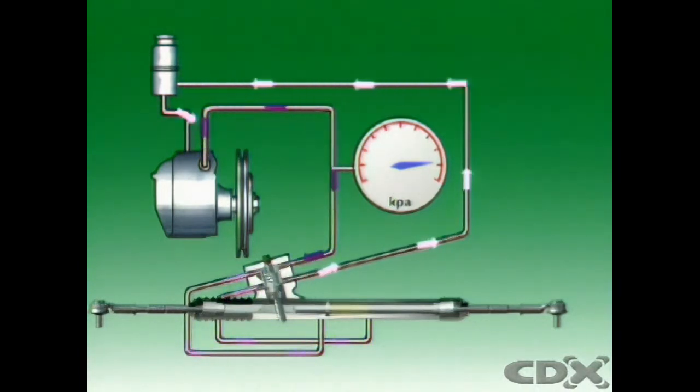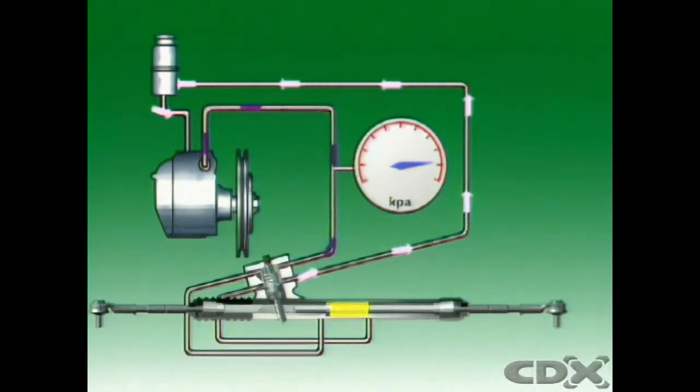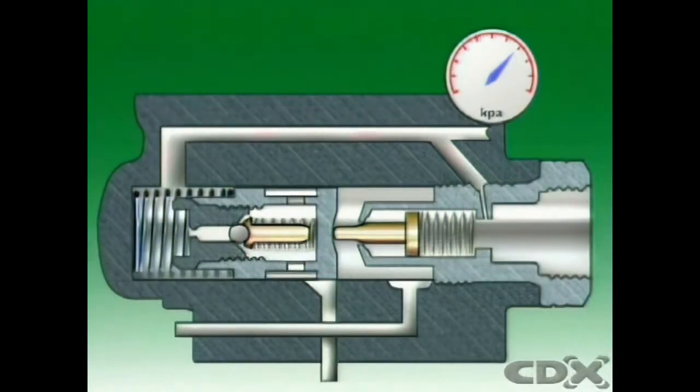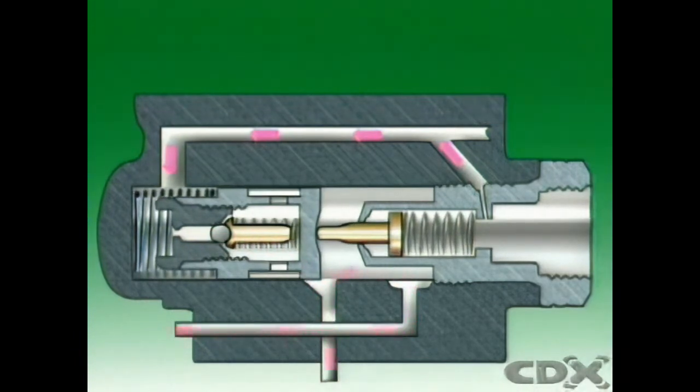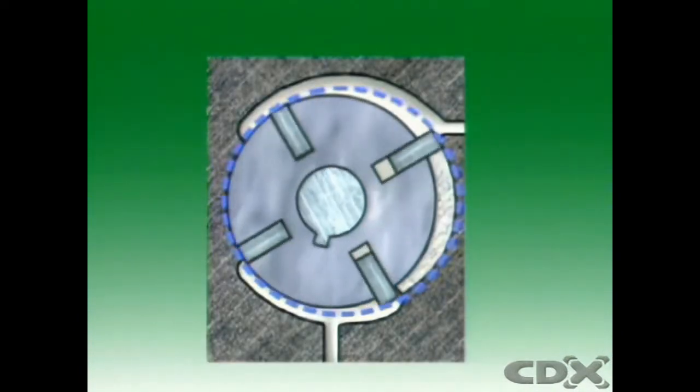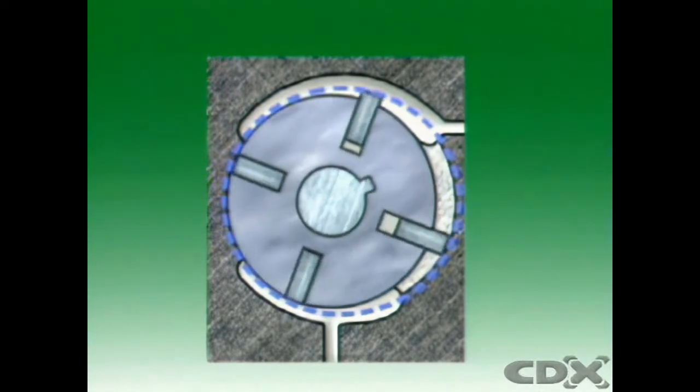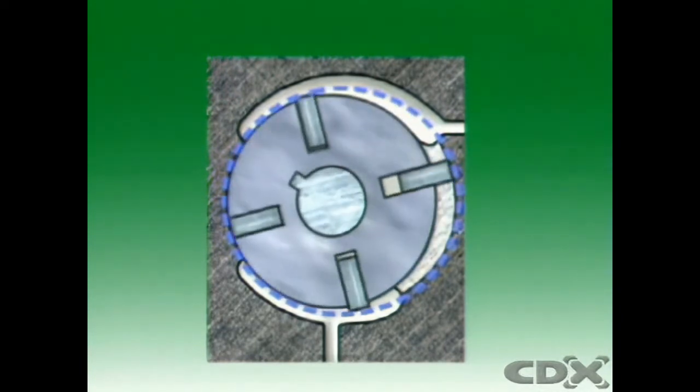With the steering wheel held at full lock, the steering rack power piston chamber becomes fully pressurized, and fluid flow stops. This high pressure is transmitted back to the spring end of the control valve, opening the pressure relief valve. A small amount of fluid passes through the pressure relief orifice, providing a pressure drop. The valve moves and uncovers the return port to the pump inlet. A predetermined relief pressure is thus maintained. The pump is normally a vane type, with sufficient capacity for all operating conditions.